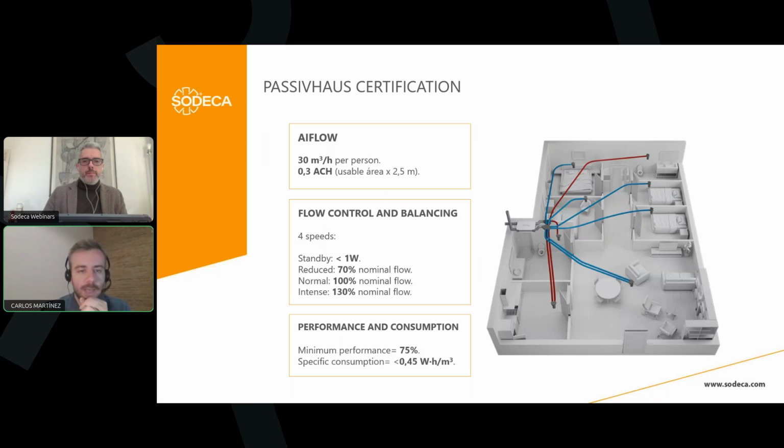Okay. We also have requirements in performance and consumption. It is mandatory that the heat recovery units have a minimum performance of 75% of heat recovery, okay? And the specific consumption of the equipment needs to be less than 0.45 watt-hours per cubic meter, okay?